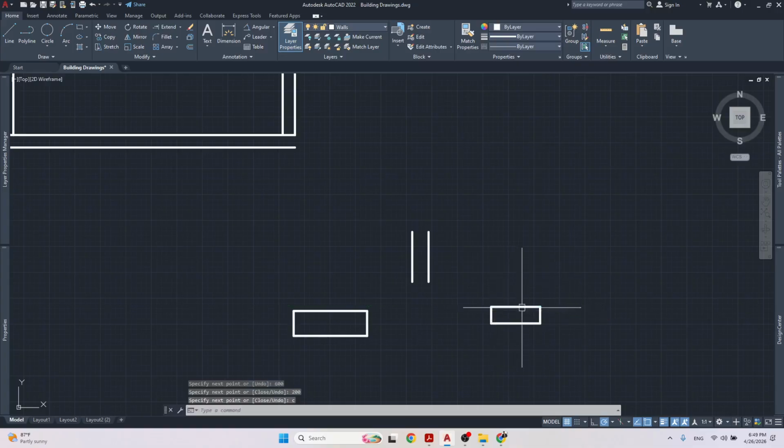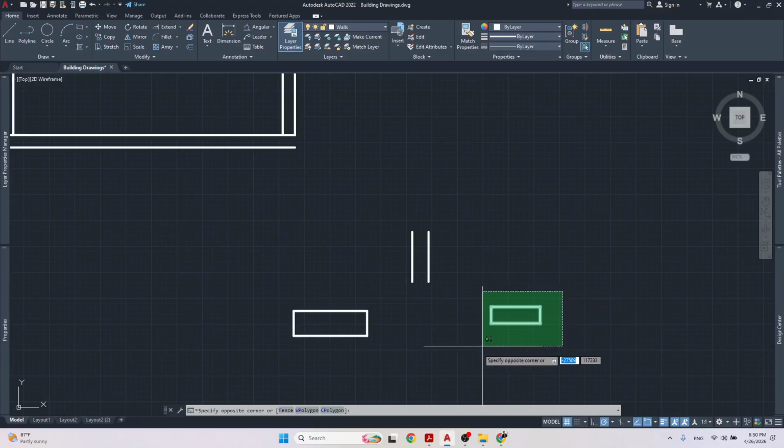Whatever they give you, if they tell you the dimensions for the footing is 300 by 900, just know that the strip footing is going to be wider than the depth. So the 900 obviously belongs to the width, and the 300 belongs to the depth. If it's 200 by 600, that is how it is. So depending on which measurement they give you, this is how you would put it in.